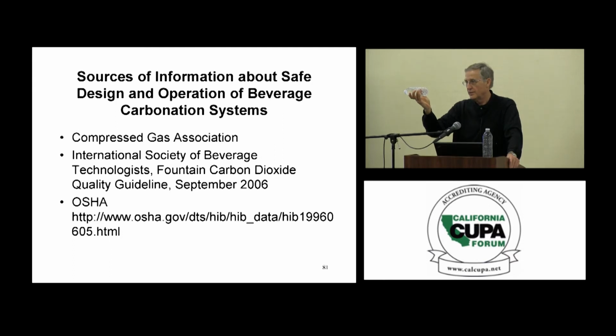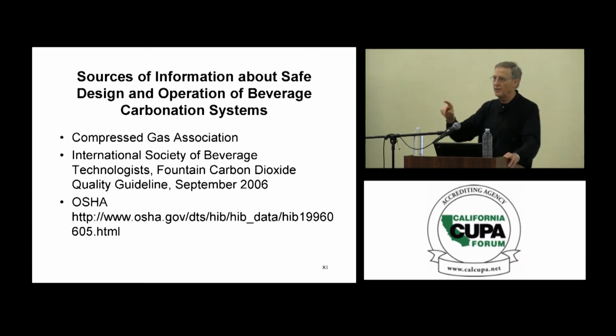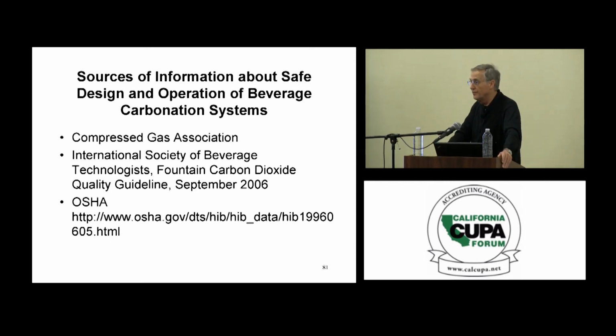So it's not a physical property of the material? No, it's the actual physical state of the material in the container that's to be regulated. So does the definition in California differ from our other national standards like the fire code and the NFPA standards? The number I have typically used is minus 150 degrees C for cryogenic fluids. I don't off the top of my head know what the NFPA standard says, but as I recall, it was minus 150 C. Boiling point? No, it's not a boiling point. It's the storage temperature.